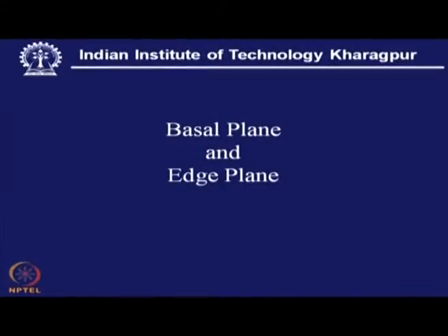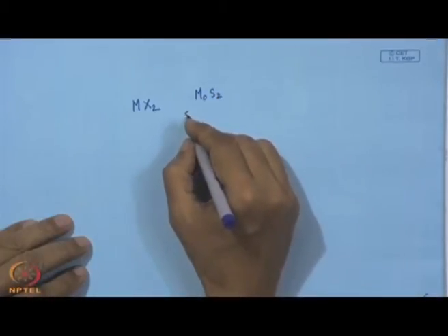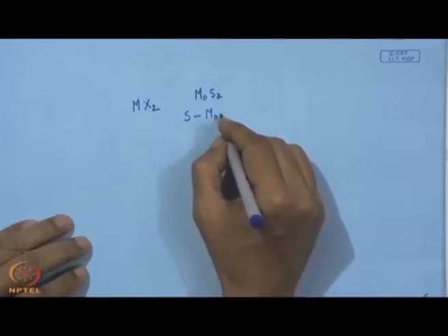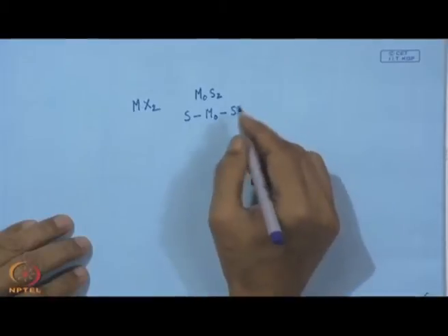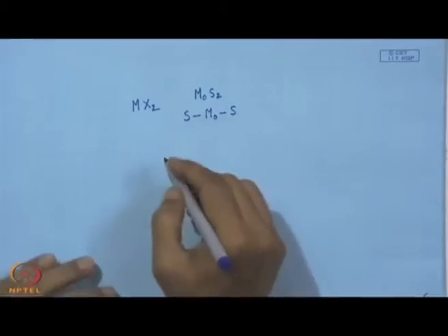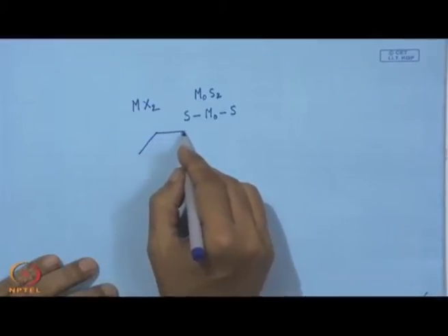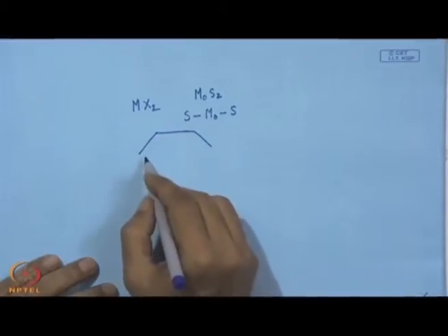So, these materials are known for their super lubricious property. Now, how is this super lubricity obtained? To look into this issue, this is actually MoS2. That means it is S, Mo and S. When we look at its structural formation, we can see that we have a hexagonal array of sulphur and molybdenum.